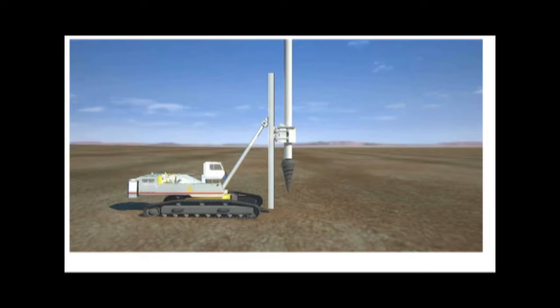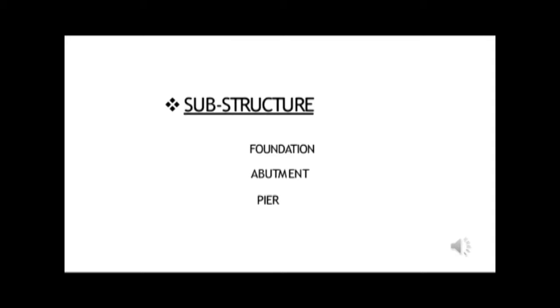Then we have temporary bridges and permanent bridges. Temporary and permanent bridges are simply classified by the usage or the service they provide. Temporary bridges are usually military bridges. They are mounted or erected easily and dismantled easily at the same time. Pontoons are temporary bridges. They are mounted, and they can even bear the load of tanks. And then we have permanent bridges. Any RCC structure or any welded steel structure is a permanent structure. That's a permanent bridge structure. So this is the classification so far.